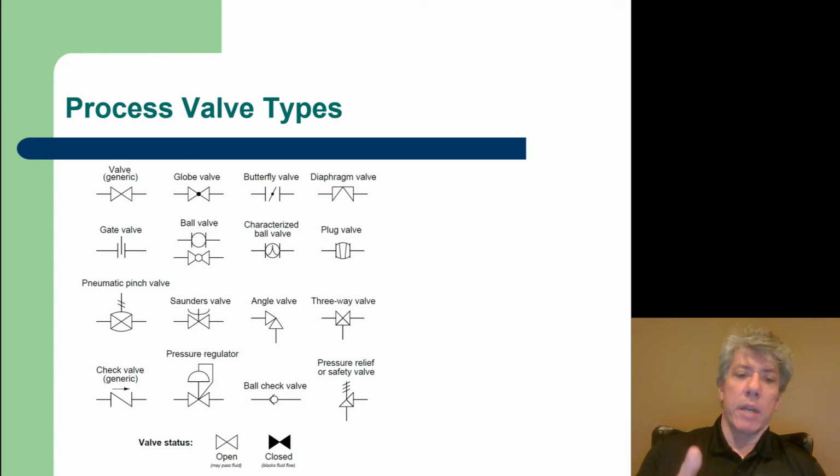That's a very common symbol for a pneumatic valve. The pressure regulator valve, though, is shown with that line from the hat going down to the body of the valve, the bow tie, to indicate that the pressure is being sensed at the valve, and that's what adjusts whatever type of adjustment there is on the valve to control it. So again, we're just keeping track of all the different types of symbols that are available, because there are many.